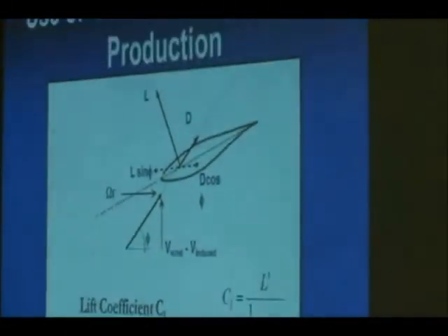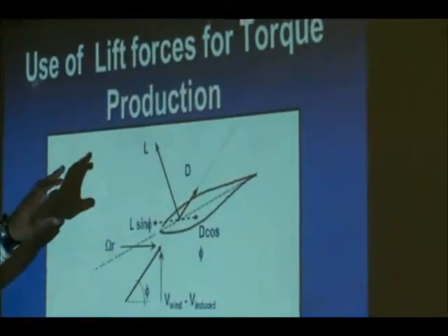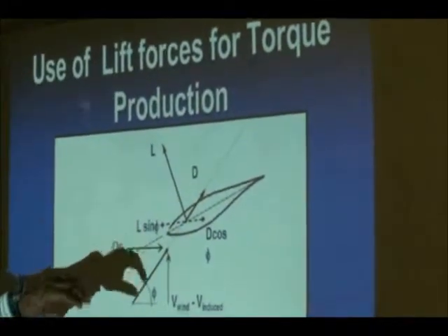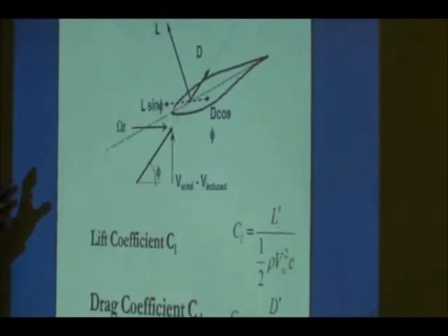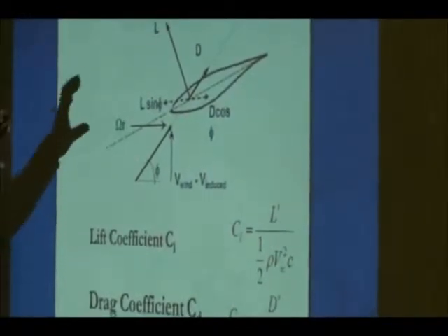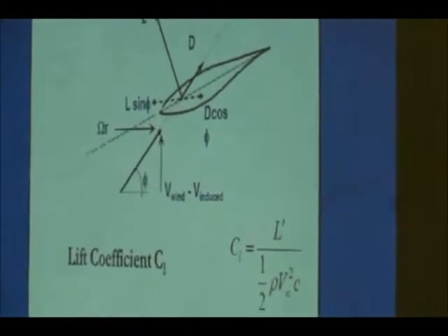The most important factor for three-bladed wind turbines is the lift that they produce across their sections. In designing a new turbine, what we are aiming to do is increase the lift force and reduce the drag. The lift force and the drag are not only determined by the wind speed available, but also by the profile of the section that's been selected.